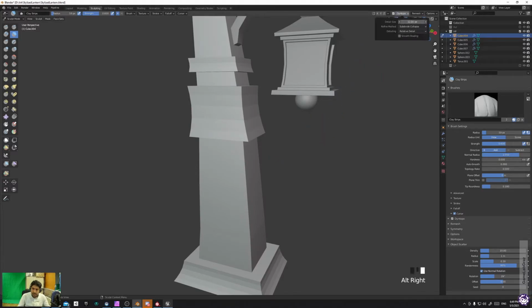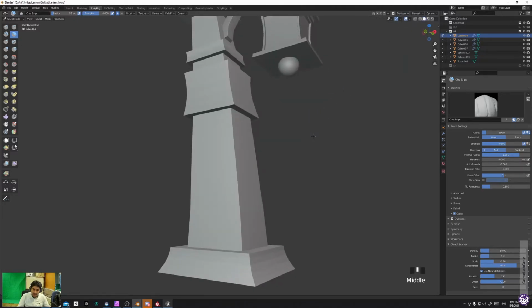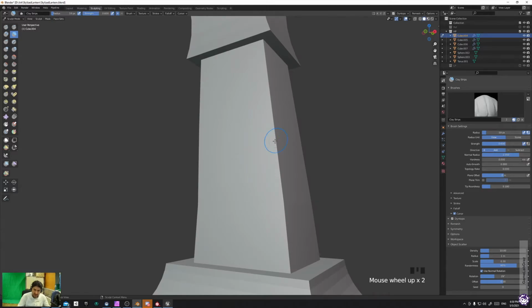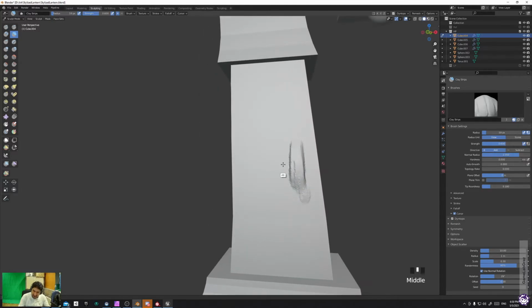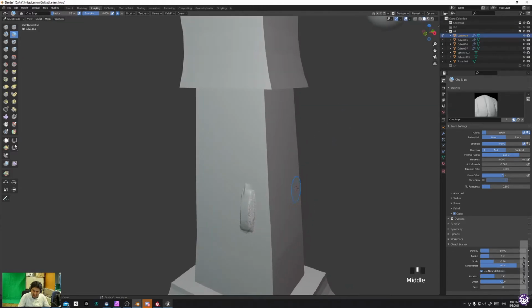Okay, here I increase the quality by reducing the detail size to something somewhat satisfying. It's not good. Yeah, I will reduce it a little bit more. However, it's too much now. Let's go for 2. I think this detail is enough. I will add it, and then from this part I can select the detailing method and put it to constant detail.